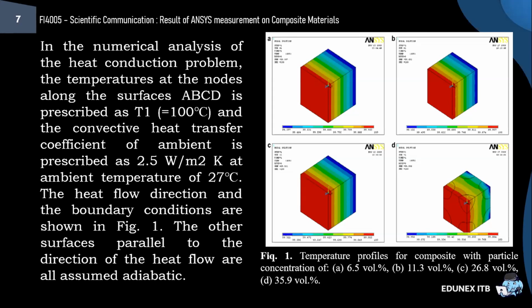This is the simulation result of the finite element method in the form of temperature of composite with particle concentration. The temperature at the nodes in the interior region and on the adiabatic boundaries are unknown. Thus, temperatures are obtained with the help of the finite element program package ANSYS.